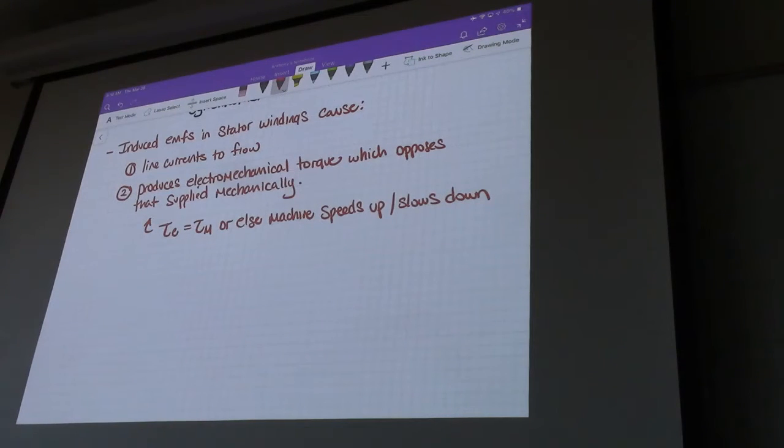It's sort of like, yeah, go ahead. So it's either they equal or you have instability, right? Well, instability, I would say, denotes... you can have an unstable equilibrium, a semi-stable equilibrium, and a stable equilibrium. With a stable equilibrium, if you deviate a little bit, it moves back. So you can leave the equilibrium value and come back to it. If you attach a greater load to the synchronous machine, it's going to have to speed up and accommodate, and then eventually come back to 60.